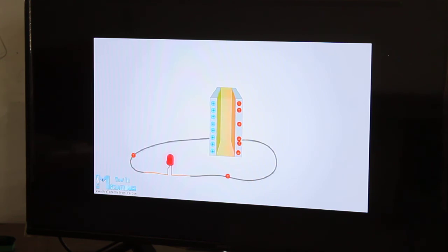Another typical example is capacitors used in DC adapters. For converting the AC voltage into a DC voltage, a diode rectifier is usually used, but without the help of capacitors, it won't be able to do the job. The output of a rectifier is a pulsating waveform. So, while the output of the rectifier rises, the capacitor charges, and while the output of the rectifier declines, the capacitor discharges, and in that way smooths the DC output.